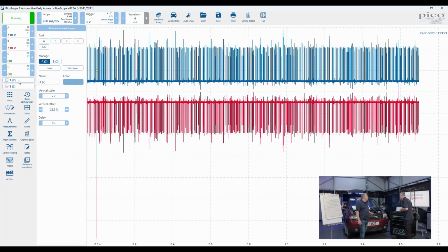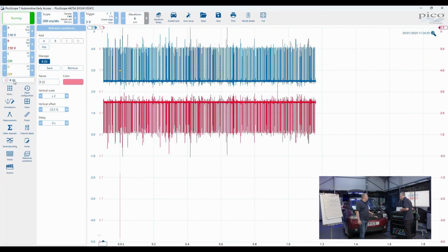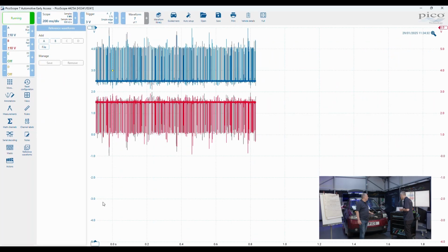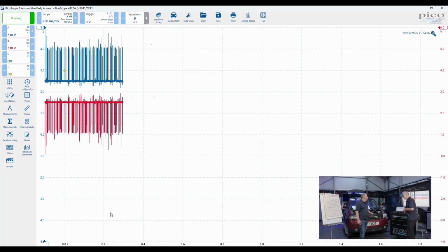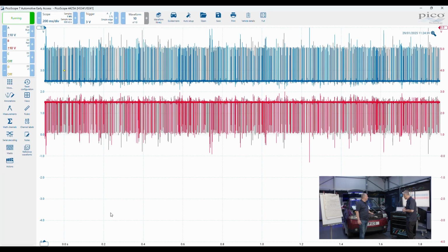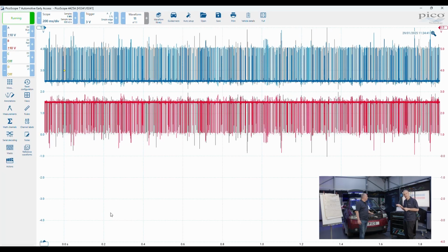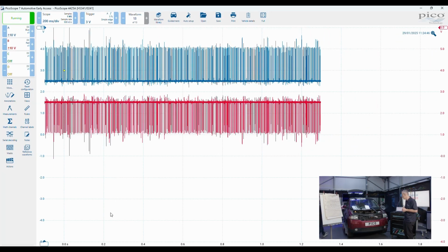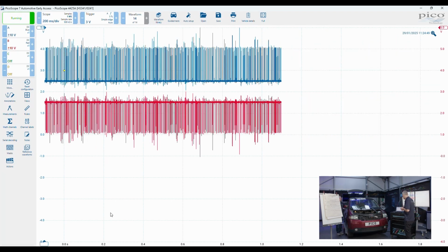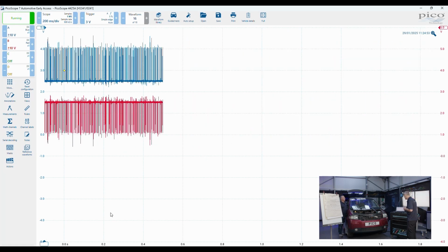You'll see that the reference waveforms have disappeared. They are actually on screen, but because we've changed the time frame, they've gone from what were captured at 50 microsecond divisions, I think it was, now down to 200. So we take that away. This is a great opportunity to see in real time where we actually turn the ignition off and capture the point where we go to recessive, and then ultimately to sleep. Whether we'll capture it in one buffer, I'm not sure. Let's see what happens. So Andy, if you can turn the ignition off.